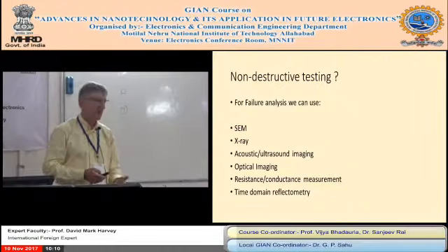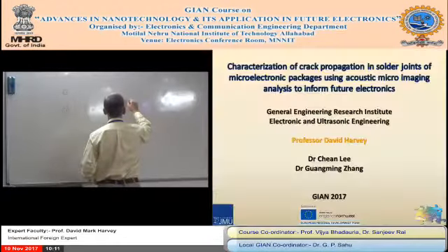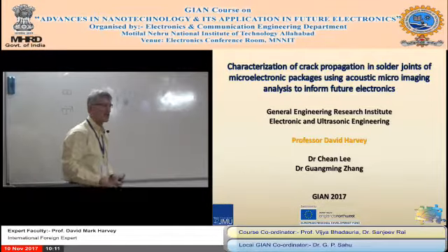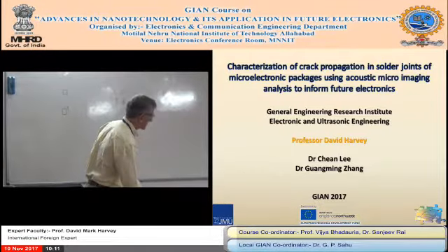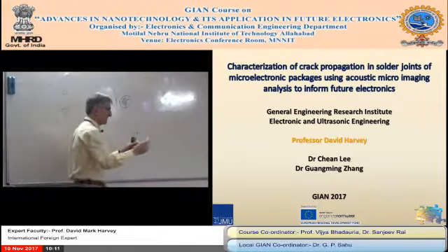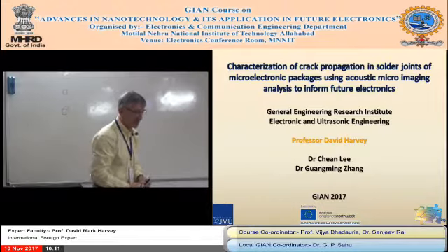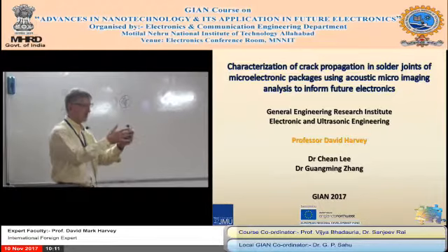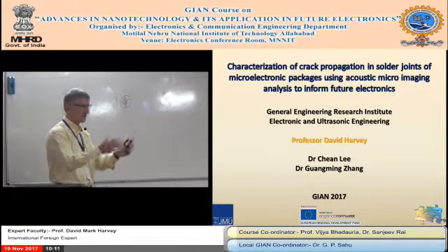But I mean, I had a bright spot in the middle, and the dark ring on the outside. And as the solder joint starts to break, this gets brighter. And the standard test we did with our initial work is we're looking for how the intensity grows. As the crack gets bigger, the reflection gets bigger.